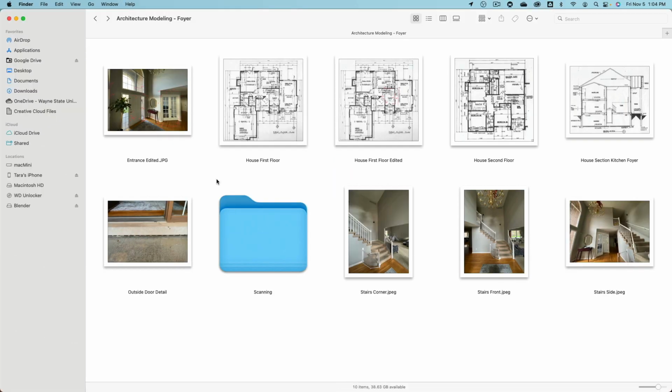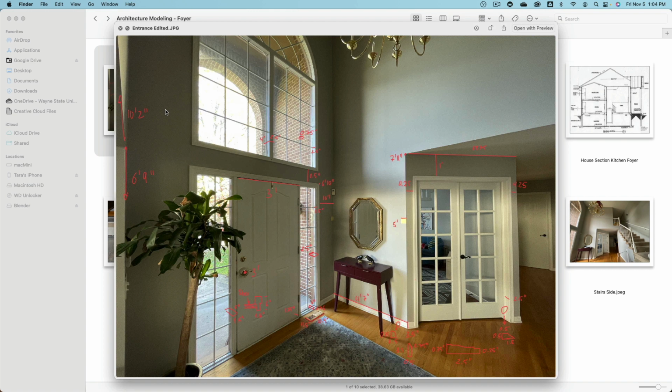At every project where you have to design something inside or for an existing space, you will face the problem of how do we get accurate dimensions. And this is something we will take a look at inside this exercise. You can, for example, go into the space and then with a tape measure and laser measurement device, take measurements, take photos like this, and then write all dimensions directly onto the photo.